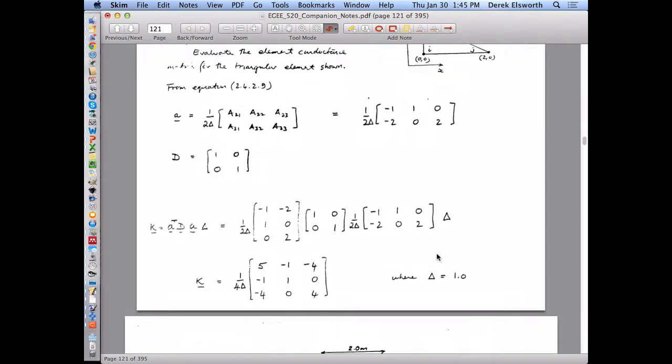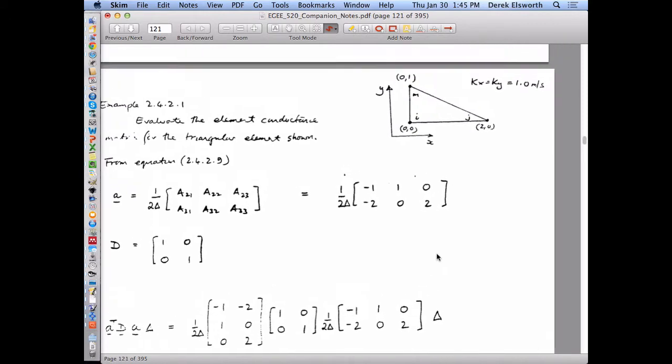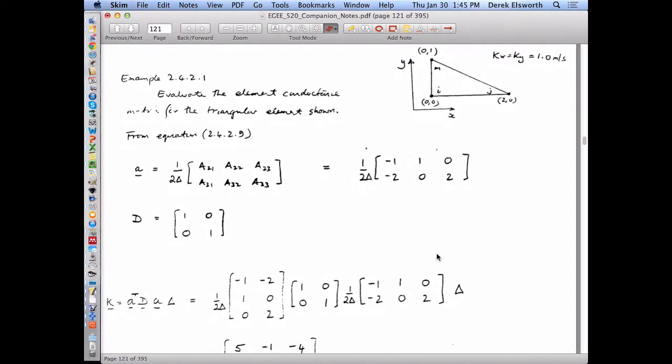So this is the deal. So, simple example. You have an element. It's of this geometry, this size. It's 1 in length on one side, 2 in length on the other side, a right-angled triangle. It doesn't matter if this is 0,0 or if it's translated to 100, 100, and the relative size of the element is still the same, 1 high and 2 wide. The conductance matrix would be exactly the same, even if it's translated through that.